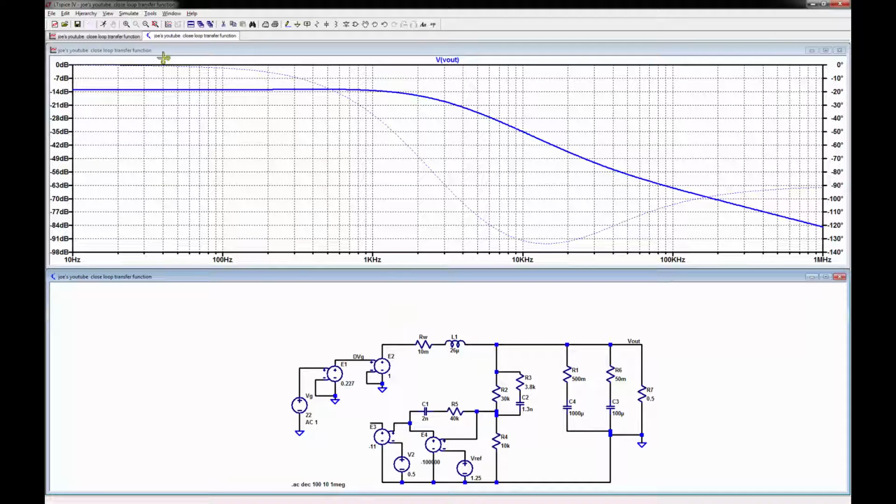Well, you could see at low frequency, what would it be? It'd be this in parallel with this stuff. Not this. These are open. At DC, low frequency, these are both open. So it'd be this in parallel with this. That's exactly what this is. Then you can see you have a low pass filter. You have the SR0. It's coming up.